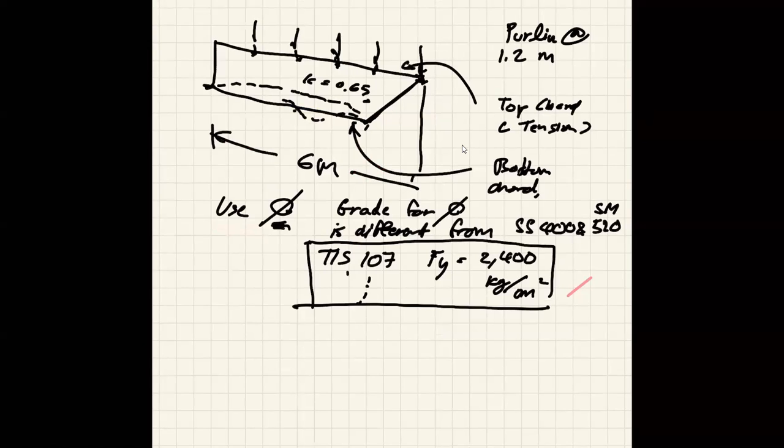So that's it for the phase number 3. You are going to design the 3 columns. Okay, and then the truss member. Oh, don't forget that you also need to design your diagonal and vertical web if you have any. All right. Don't forget your web.